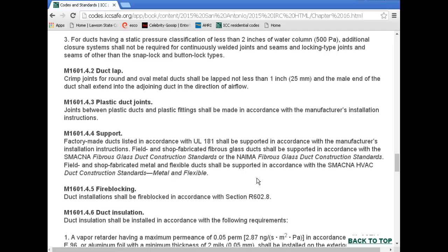And if I had a 15, I would put an asterisk and put this in there. Because I bet you, if this is a test question, they haven't gone to this. They're going to use this old one. Metal ducts shall be supported by a half-inch or more wide, 18 gauge strap.